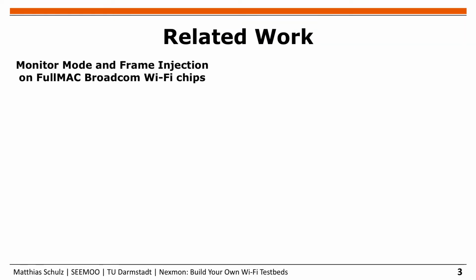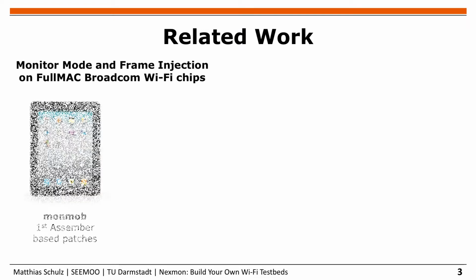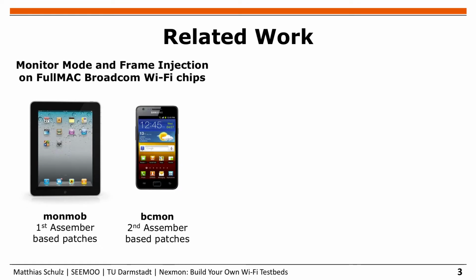So regarding related work, our first intention when we initiated the project was to get monitor mode and frame injection running on a Nexus 5 smartphone, therefore also the name Nexmon. There were two other projects also doing similar things on older devices like MonMob and BCMon. Those are projects just activating some extra features in these FullMAC devices.